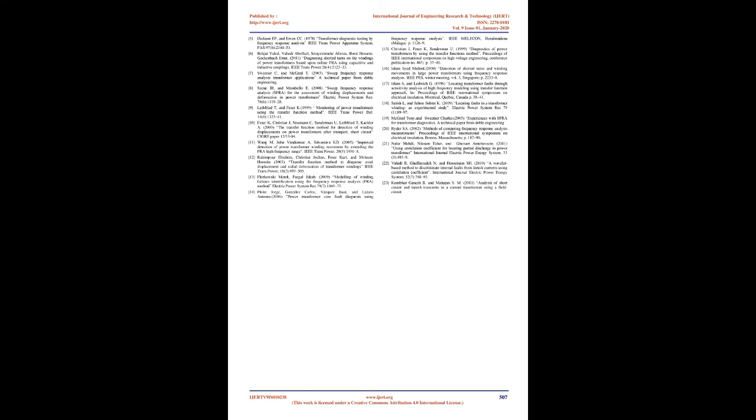than 0.2% of turns along the winding, was performed on a real distribution transformer. A method which assures sufficient reproducibility of the SFRA measurements was explained. The experiments on a distribution transformer for estimating the sensitivity of different transfer functions in detecting of interturn faults were discussed. It was found through the experiments that the voltage gain measurement across the HV winding of the transformer with other windings floating and not shorted is the most appropriate configuration for detecting interturn faults along the windings.